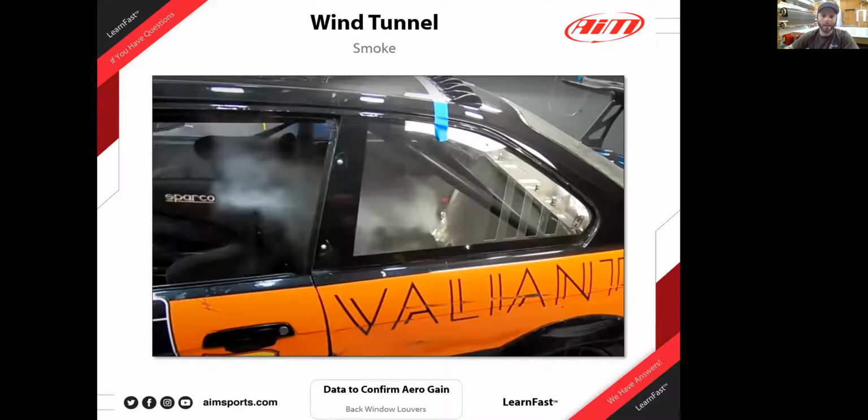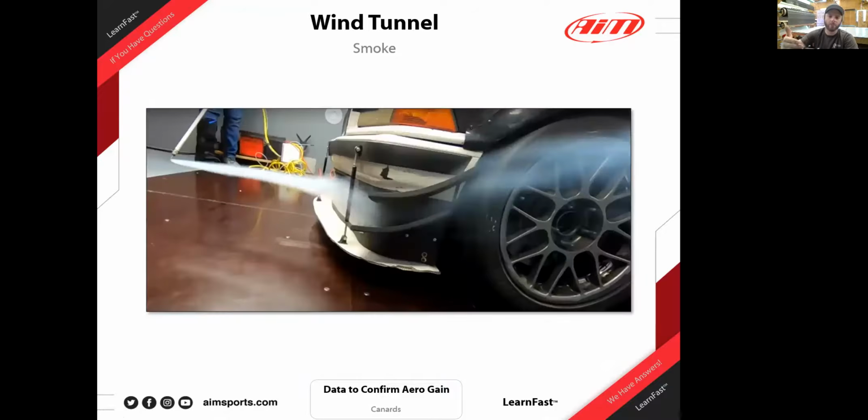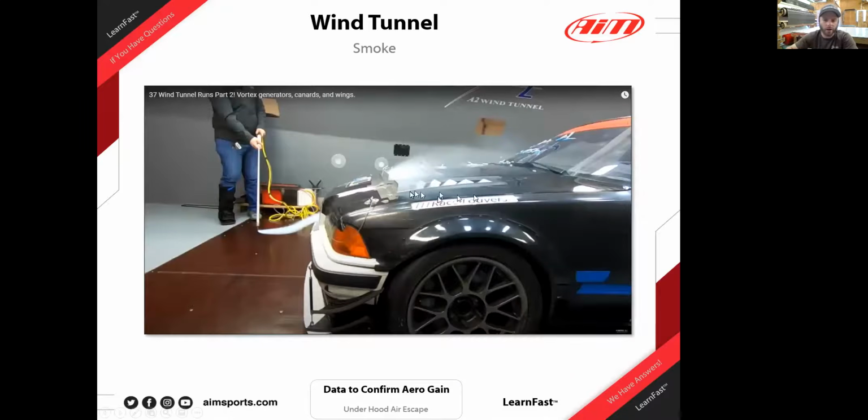Right. Yeah, it depends where your radiator is a little bit, and how steep your windshield is. That high pressure bubble at the cowl on a steeper windshield car might come forward a little more along the hood. You can always wool tuft louvers and see where that bubble is. So yeah, it's important. It's easy enough to be in the ballpark.